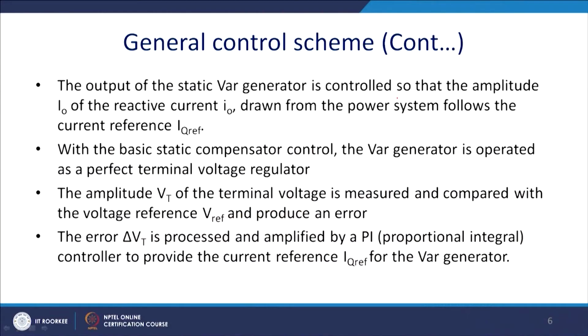The output of the static Var generator is controlled so that the amplitude IQ of the reactive current drawn from the power system follows the reference current IQ ref.